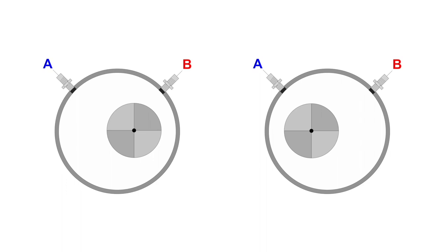The center line is the measurement of shaft position during run-up. We use the run-up module in the analyzer. We need to set the trigger properties. The run-up measurement is the series of individual readings. Each reading must be triggered. For turbine analysis, we usually use the triggering by speed and time.